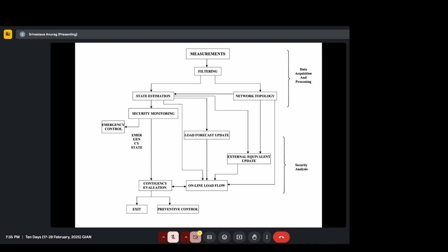Mesh network in distribution system is rare. If there are any, it will be less than 0.5% in a much bigger city. Mesh network is more reliable because if you miss one path to reach a data point which is consuming the power, you can reach it from another path, right? In a radial network, that will not be possible, because you're going to only feed, and we will talk about that more later in distribution system modeling.